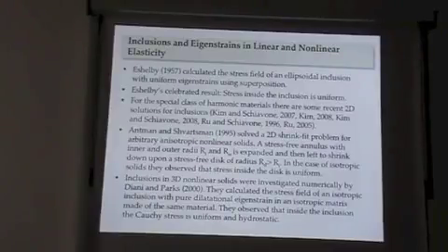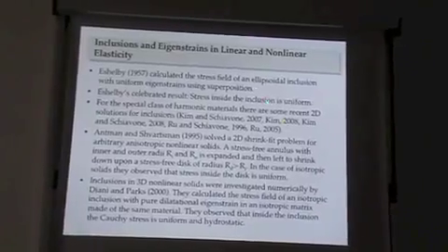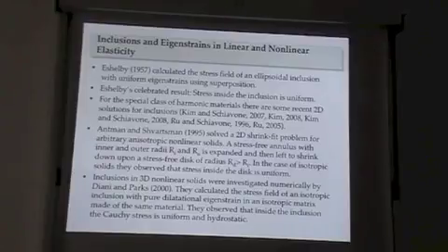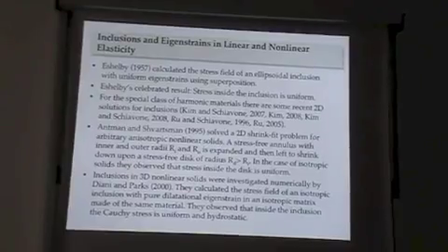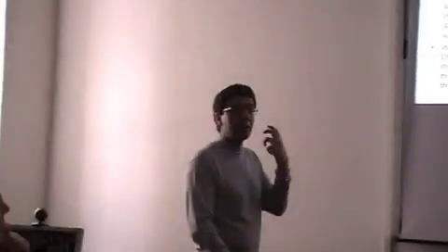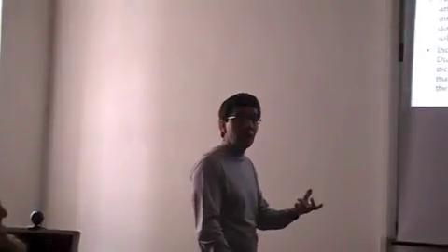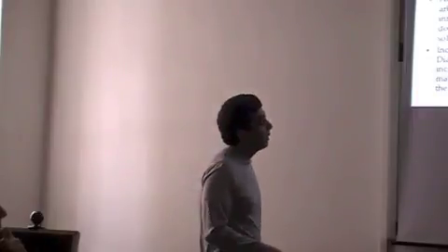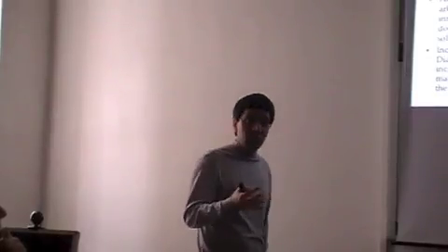He looked at an ellipsoidal inclusion in an infinite solid, everything linear, isotropic, elastic, and he assumed that the eigenstrain is uniform in the ellipsoid. And then what he proved was that the stress inside the inclusion is also uniform. Very surprising result. So now my goal is to extend this to nonlinear elasticity.